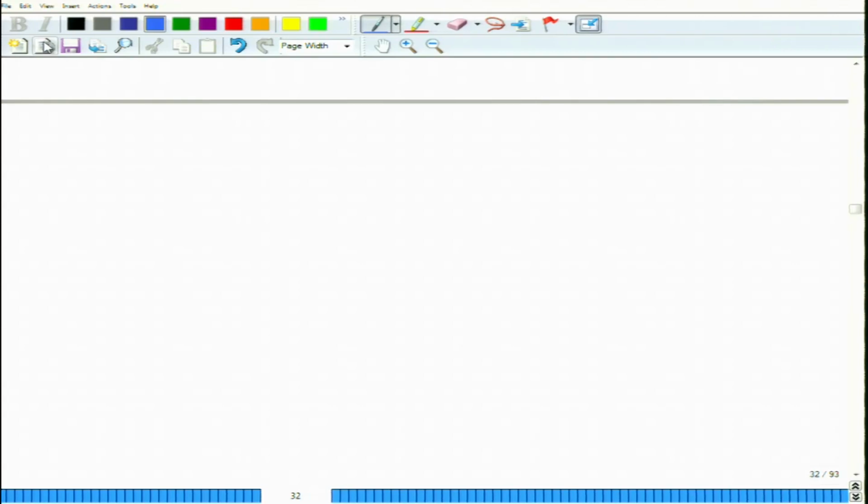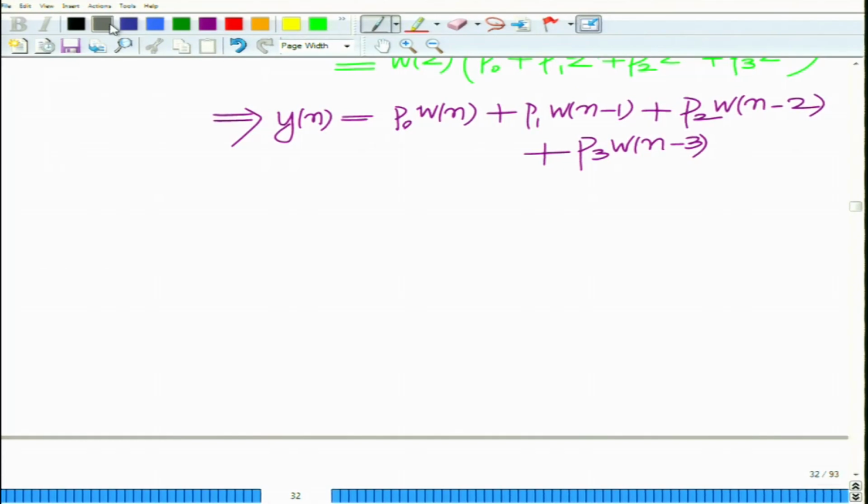And now once again, similar to what we did for the direct form, what we want to do here is interchange these two branches, and once we interchange these two branches, we can see that the resulting delays, and in this case in fact even the adders, can be combined for both the branches. So, once you combine them, you will get the representation with the minimum number of delays and adders. So, what we are going to do again here is interchange branches and merge the common delays and adders, okay.